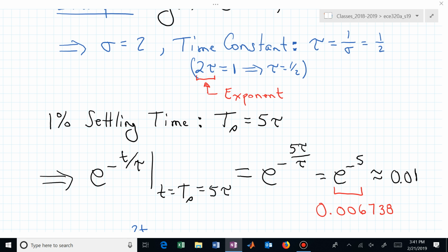And 1/2 being a time constant is very, very big in electrical terms. Usually a time constant is much smaller than that. So when you excite or initialize a circuit, it doesn't take long for those voltages and currents to die away, to become gone. Or what do we consider to be gone? When they're 1% of where we started, after 5 time constants.